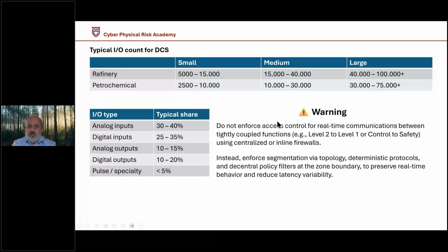And if you have flow measurement, it needs to be very fast because flow is very dynamic, just like pressure is a very dynamic signal. So you may measure that on a high sample rate, sometimes even a second sample rate or even faster. Where if you have a level measurement, that's much less dynamic. So then you can have lower sample rates.